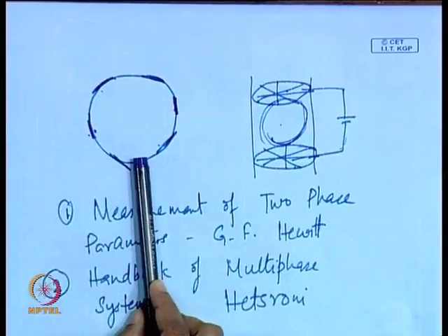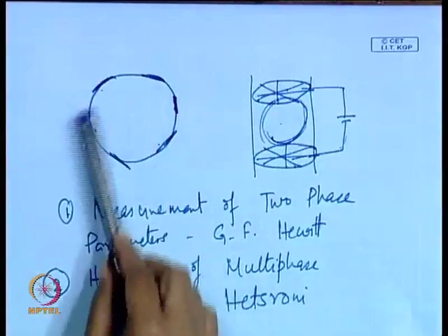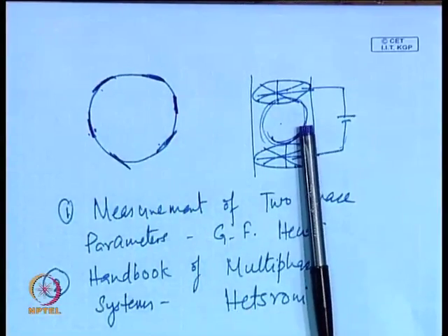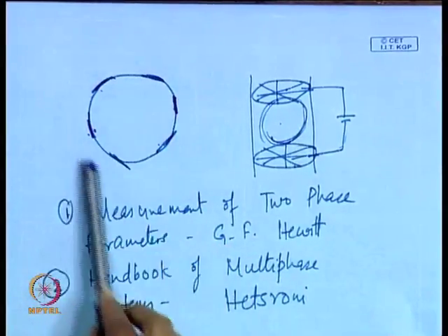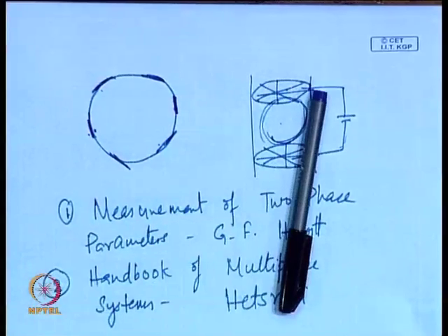The design is very important for this particular case. And for circular pipes, I had already shown you this rotating field gauge, this is more or less useful. If it is a non-circular channel, then definitely this rotating field sort of a thing is not possible, because the symmetry does not hold.